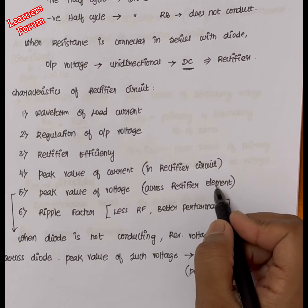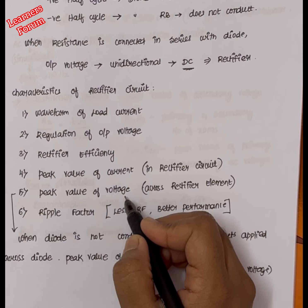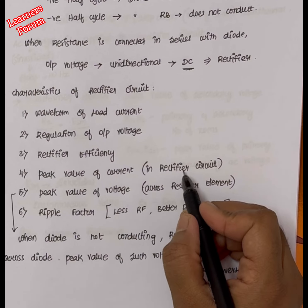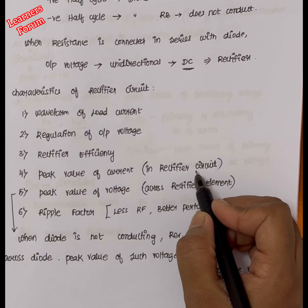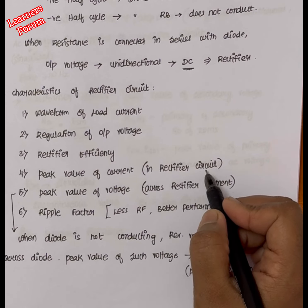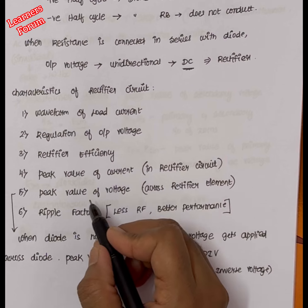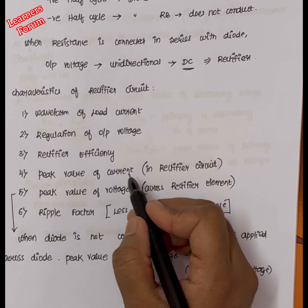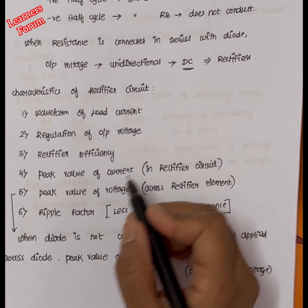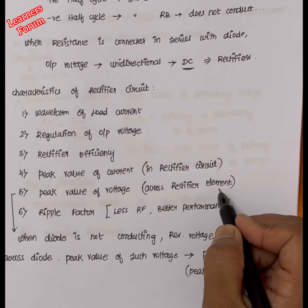So across the diode, when we are calculating the peak value of voltage, that is also to be included under the characteristics. In a rectifier circuit, we will be calculating the peak value of current across the load which is connected to the circuit. So this is the ultimate difference between peak value of current and peak value of voltage. Peak value of current is taken across the load, whereas peak value of voltage is taken across the diode, which is nothing but the rectifier element.